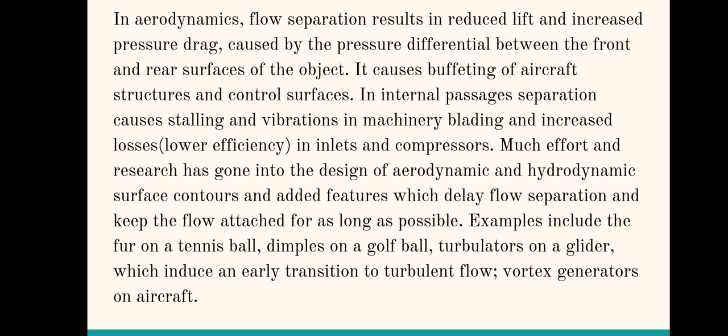In internal passages, separation causes stalling and vibrations in machinery blading and increased losses, that is lower efficiency, in inlets and compressors. Much effort and research has gone into the design of aerodynamic and hydrodynamic surface contours and added features which delay flow separation and keep the flow attached for as long as possible.